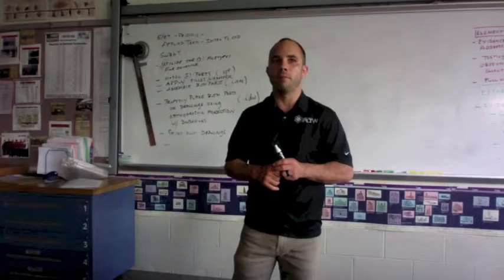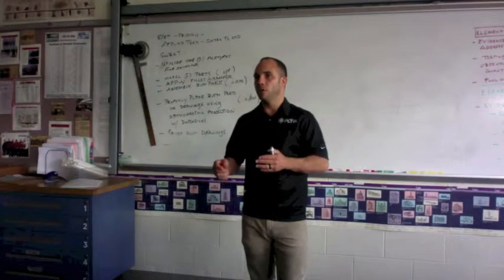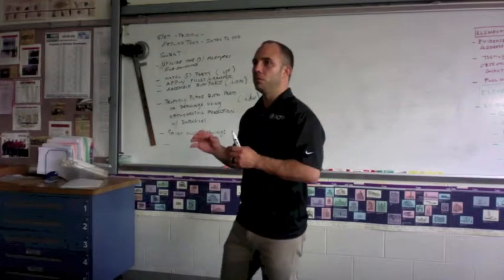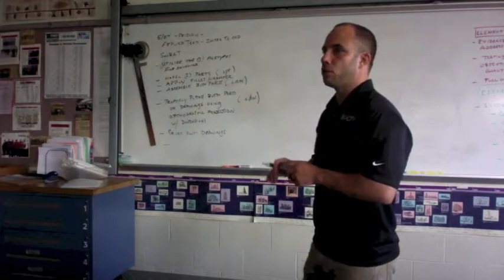Like I said before though, we don't need to show all 6 sides on a drawing. We have to show how many? 3. Okay, they are usually the front view, the top view, and the right side view. And then usually an isometric drawing with that.